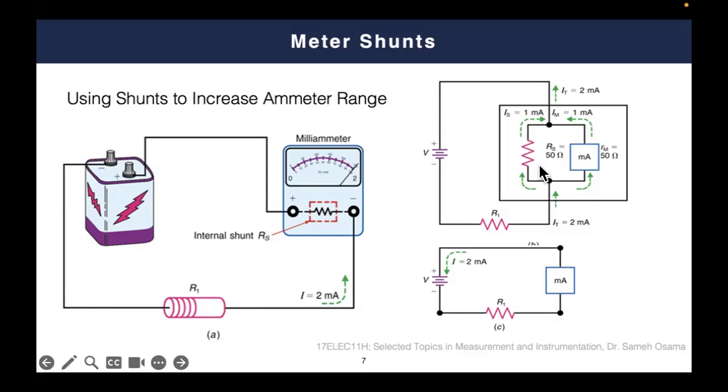Typically, what happens is that the current will be divided. 1 milliampere will go to the coil, and another 1 milliampere will go to the shunt resistance. Herein, the deflection will be proportional to the 1 milliampere you introduce. So, for example, if the current here is 1.8 milliamperes, then 0.8 will move here, and 0.8 will move here. 0.8 means here 80% of the full scale range.